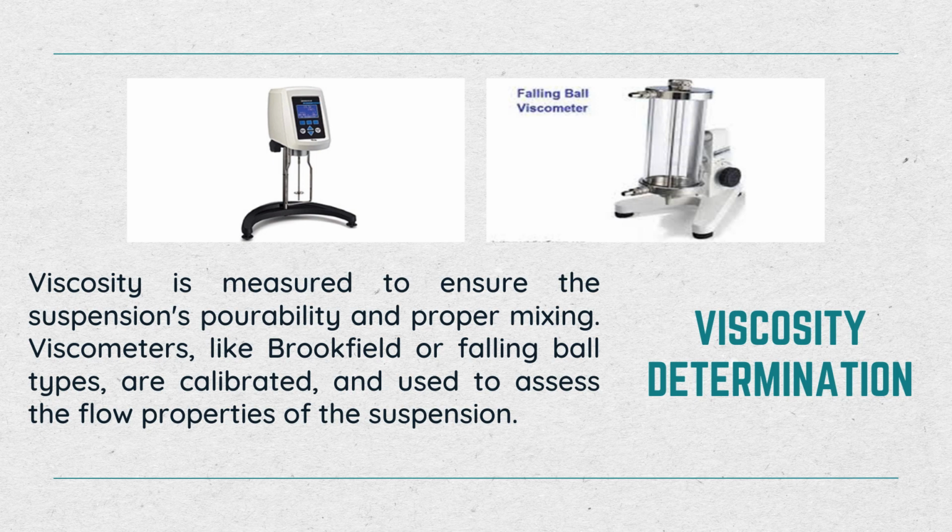Viscosity determination. Viscosity is measured to ensure the suspension's pourability and proper mixing. Viscometers, like Brookfield or Falling Ball types, are calibrated and used to assess the flow properties of the suspension.